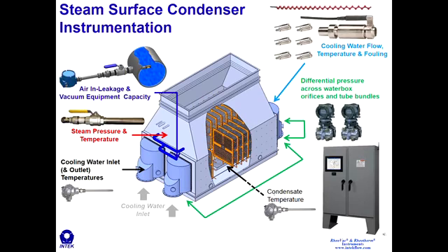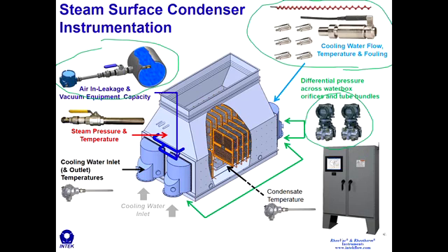So that concludes all of the instrumentation for both basic and advanced studies. So I want to show some case studies where now all of this instrumentation has been put into place, and we've identified issues with condensers and implemented retrofits and increased the performance of these particular condensers. So this slide is a nice summary slide for the instruments that we would recommend for various reasons. Differential pressures for flow and macro fouling, a ReaVac tool for monitoring all non-condensable related degradation mechanisms, pressure, temperature, and then tube sheet monitors for taking a look at the design of a condenser.